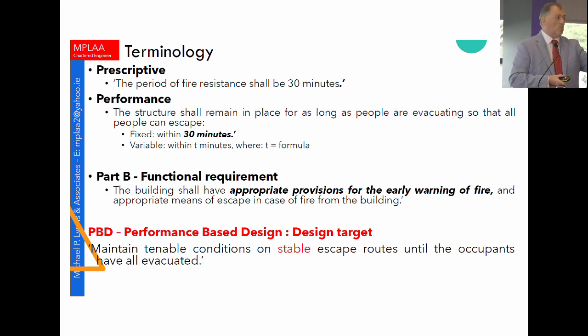You must decide what the relevant travel distance is. You must decide what the fire rating on the floors and the walls are, how combustible the wall and ceiling linings are. All of those simple decisions that TGD B does for you are actually back onto your court and onto your liability. And the assessing fire officer or building control officer has to agree with that as well when they accept that design and make a recommendation in relation to granting a fire safety certificate when it's a performance-based design.